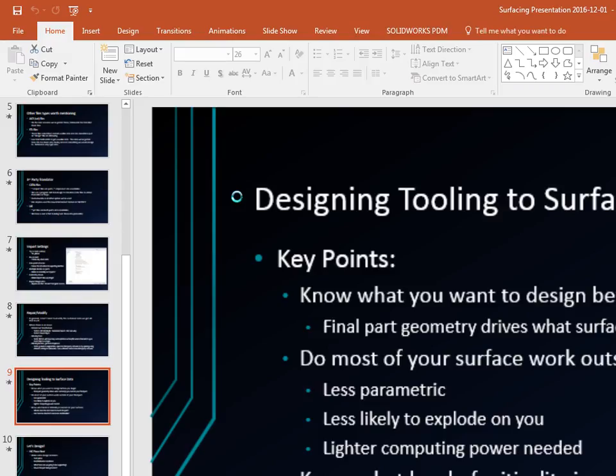Okay. If you wanted to do what you're doing there, you definitely want to do it before you start putting all these fillets in. Yeah, that's definitely true. Okay, so I'm just going to do a simple replace face here. So I need a planar surface. Nope, sorry, I need a plane that is 2 degrees off.